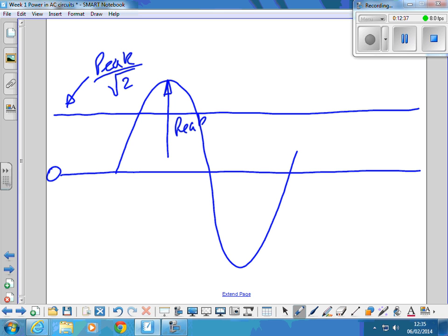To do that, you need to spend about 2 or 3 times as much money on the meter to get a true RMS meter that actually measures the RMS value and not an average converted. I'm not up to date with the current costs of instruments, but there always used to be a considerable difference. When I was in the industry, you probably had to pay £700–800 for a good quality true RMS multimeter. You only spend that money if you need it, really.